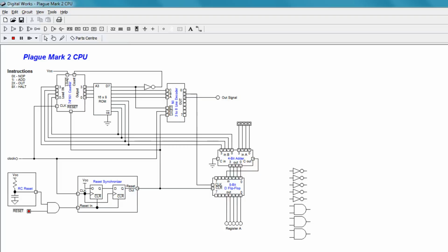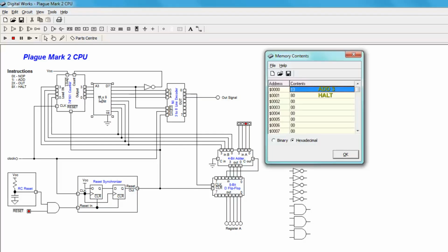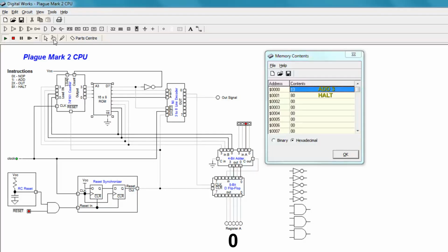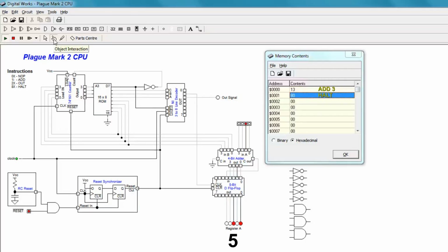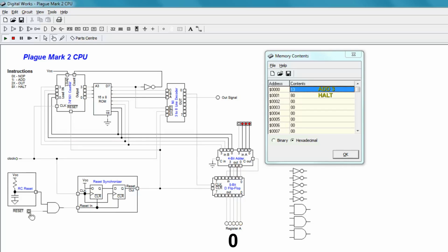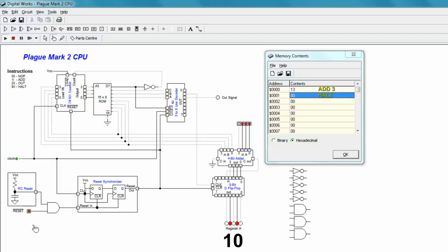Notice that I added the AND gate here, and placed 3 unused gates by the unused inverters, since I'll be using a quad 2-input AND IC on the breadboard. So now I'll set the switches to 2 and run this without first resetting it. And we get 5. I'll try a value of 7 with the switches. I'll release the reset switch when the clock is low. And we get 10, which is 3 plus 7.